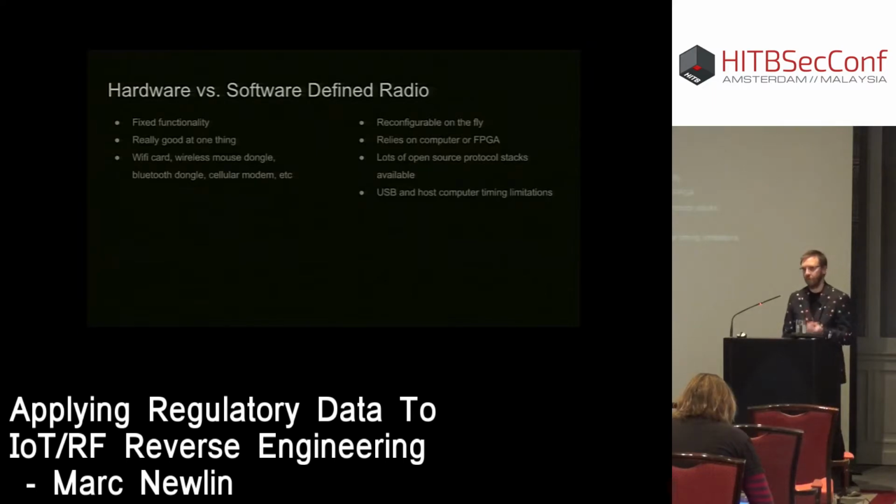useful. So software-defined radio allows you to have a high degree of reconfigurability. So you might have a wide range of frequencies you can tune to, varying bandwidths. But the drawback is that it doesn't know how to do any one thing. So the SDR will just send this raw radio data to your computer or to an FPGA. And then you have to implement the functionality that makes it a Wi-Fi radio or a Bluetooth radio or whatever. But it's a very useful tool for doing this kind of reverse engineering because you can reconfigure it on the fly as you're figuring out what it is that you're looking at.